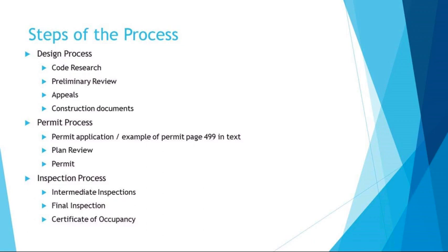Once the project is complete, the inspector will do a final walkthrough to confirm final compliance with the codes and to make sure that the space is ready to be occupied. When the final inspections are completed, the construction of the project is typically considered finished. However, before anyone can move in, there are different types of certificates that you've got to have.